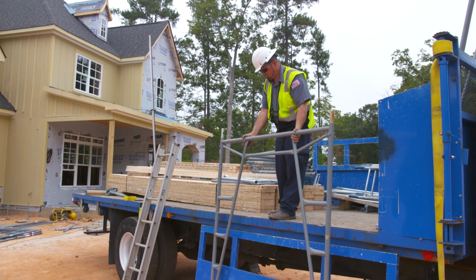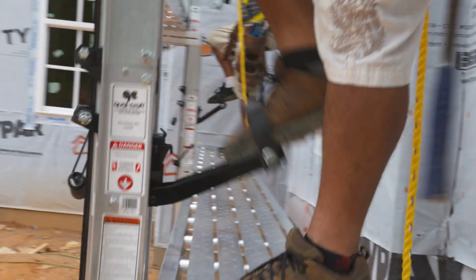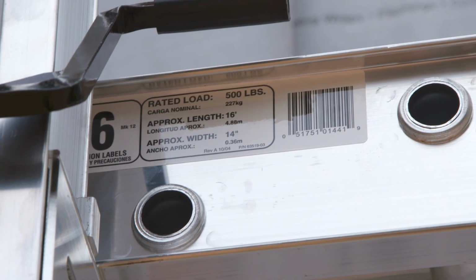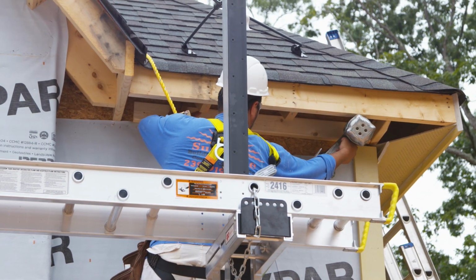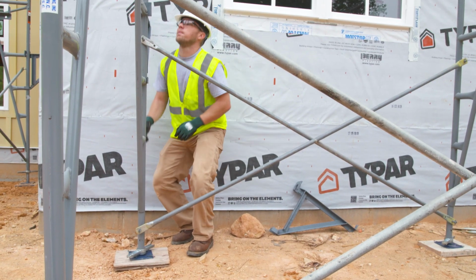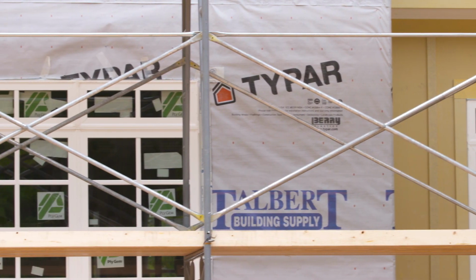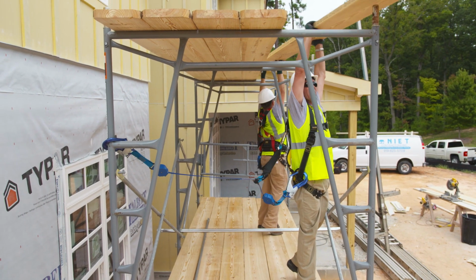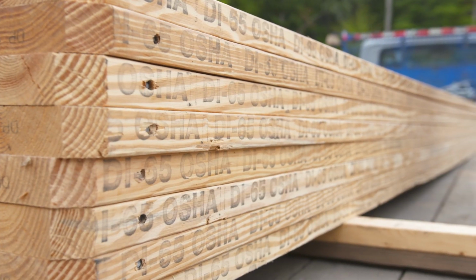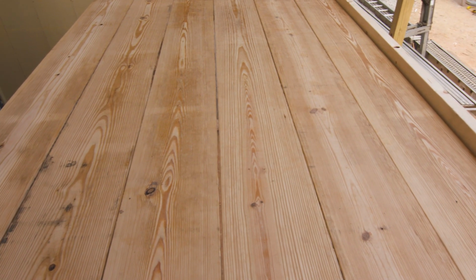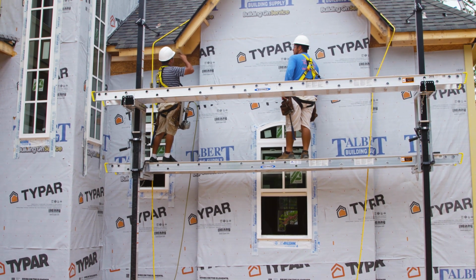It's important to know what the load capacity is of the scaffold to avoid collapse. A scaffold must be able to support its own weight and at least 4 times the intended load, which includes workers, tools, equipment, and materials. Bracing is extremely important. Scaffolds should never be used unless all required bracing and securement is in place. Scaffold platforms must be fully decked and at least 18 inches wide. Only scaffold-grade planks should be used. Planking can be wood, metal, or a combination, and must be secured to prevent movement.